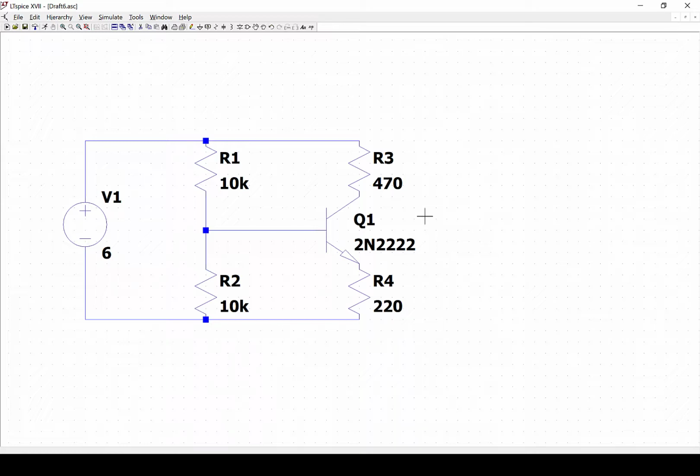But there is one very important thing which is missing, which is a voltage reference. And typically in our simulator, also in reality, you want to know basically what's the 0 volt reference for your circuit. And you can do that by adding a ground. You see here, I click here, ground to your circuit. So basically, this is my ground reference, the 0 volt for my circuit,